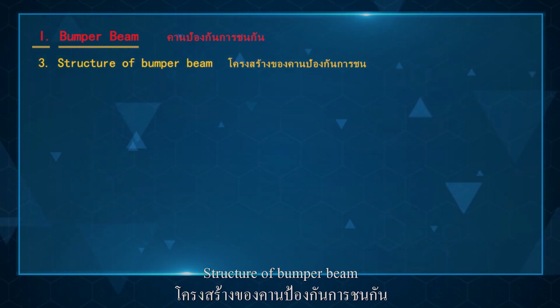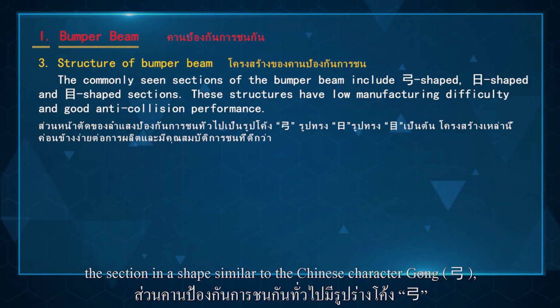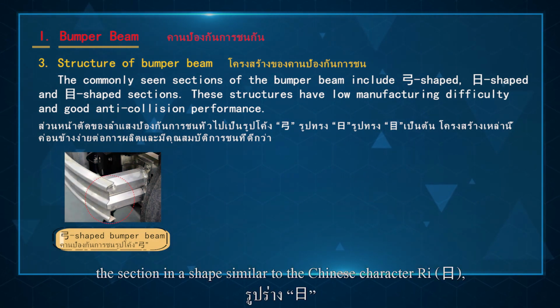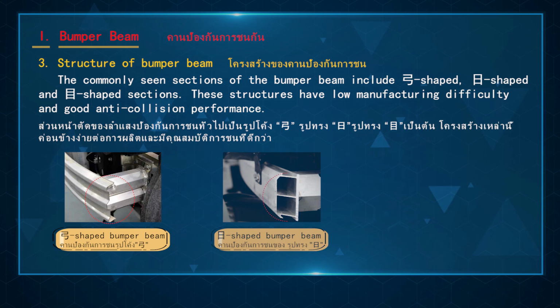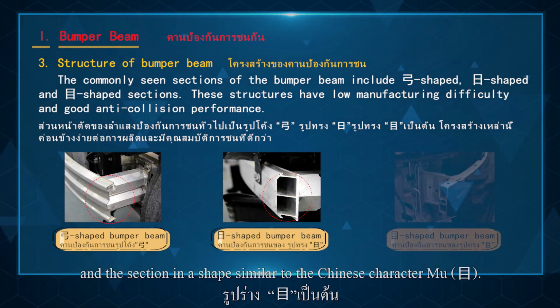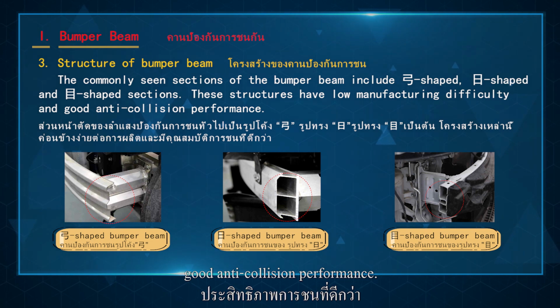Structure of bumper beam. The commonly seen sections of the bumper beam include the section in a shape similar to the Chinese character Gong, the section in a shape similar to the Chinese character Zhi, and the section in a shape similar to the Chinese character Mu. These structures have low manufacturing difficulty and good anti-collision performance.